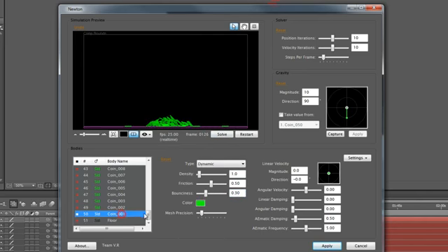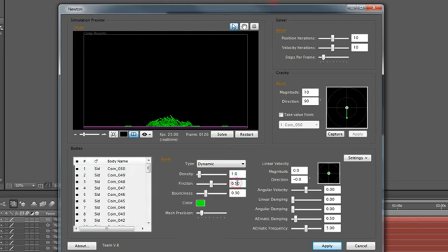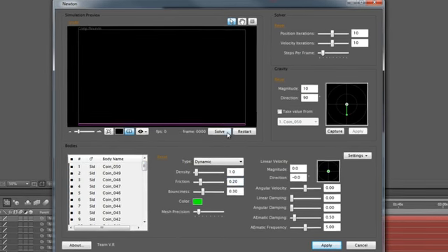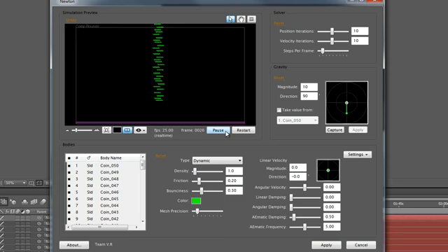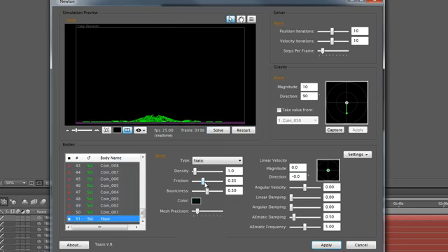Okay, now as for the coins, let's give them less friction, 0.2. Give some more friction to the floor, let's say 0.6, see how that looks. And take off that bounciness. Okay, we're getting there.